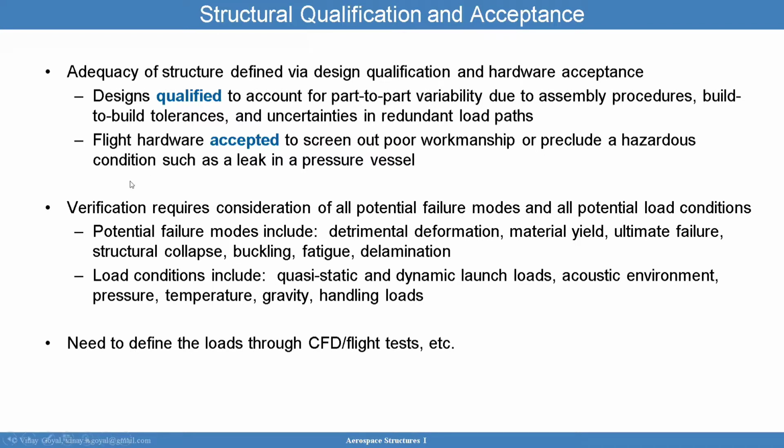And so two types of tests. One is a dedicated qualification test article that you may never fly. In some cases you can fly it, but most of the times you don't. And then another test is strictly done for every flight unit to ensure that you have screened it out for any workmanship issues. The verification requires consideration of all the potential failure modes and all potential load conditions.